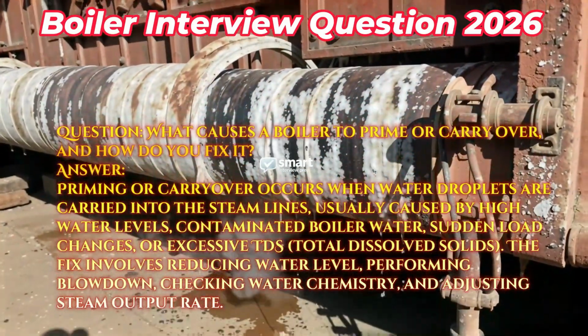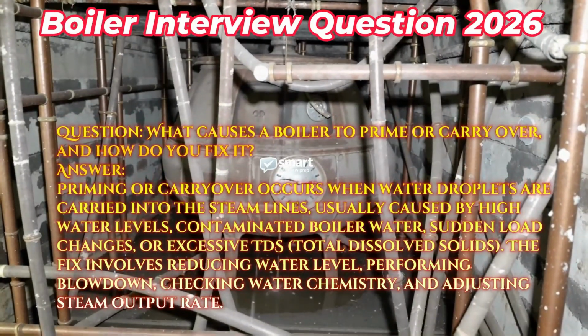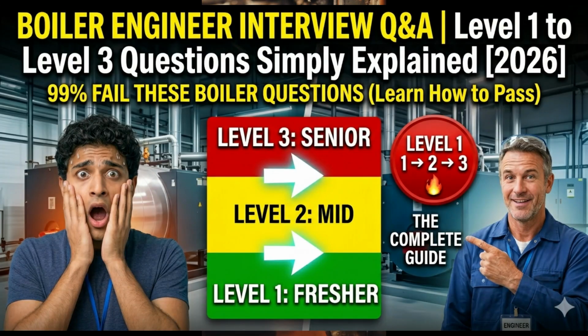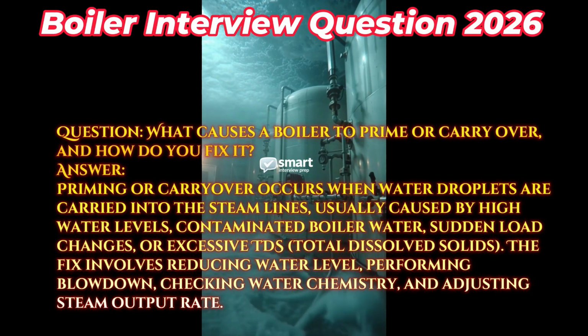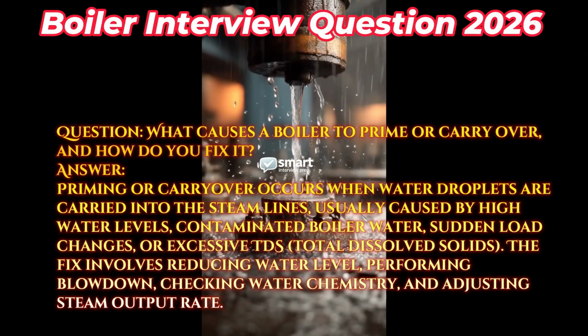Priming or carryover occurs when water droplets are carried into the steam lines, usually caused by high water levels, contaminated boiler water, sudden load changes, or excessive TDS, total dissolved solids. The fix involves reducing water level, performing blowdown, checking water chemistry, and adjusting steam output rate.